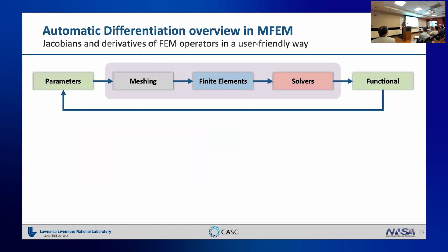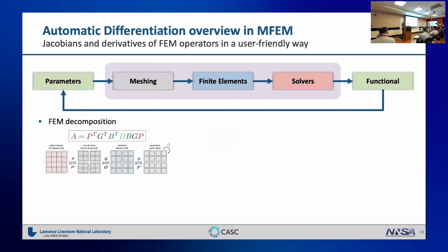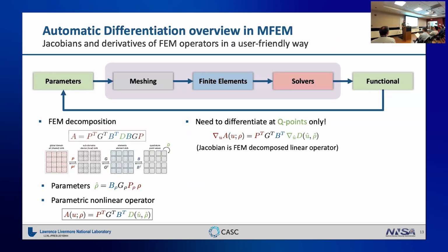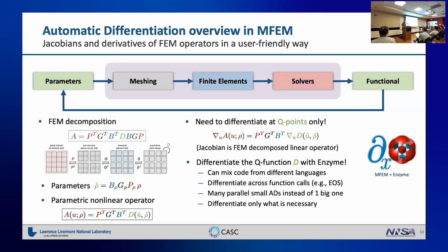Okay, so AD overview in MFEM. We utilize the decomposition to only do derivatives at quadrature points. We have a description for a parametric nonlinear operator, and we need to do the derivatives at quadrature points only. And this makes this whole DFEM interface possible.